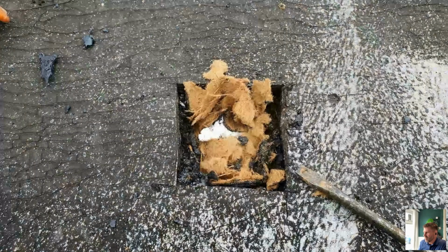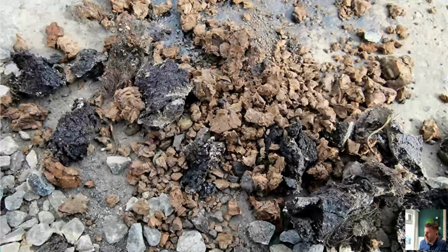There's also composite boards that you might find out there. I haven't got a live example of this, but you might find a cork composite board where 20 millimeters of cork was bonded to the top of a PUR board. That was because the PUR had better insulative properties, but you could fully bond to the cork. That was something that was around in the 80s, 90s, a cork PUR composite board. So you might dig down through the cork, and you always should, to find out what depth it is, and you might find PUR underneath it.